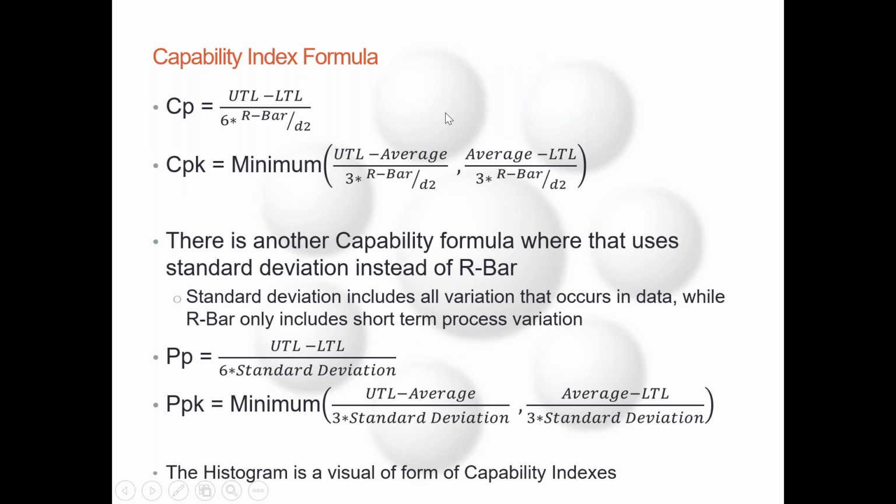For anybody that wants to see the formulas, I wrote them out here. They're just formulas. Again, use your SPC software. It'll do the calculations for you, and you don't have to worry about it. Now, also notice we have a CP, CPK and a PP, PPK. Not everybody uses the PP, PPK. They just call everything CP, CPK.